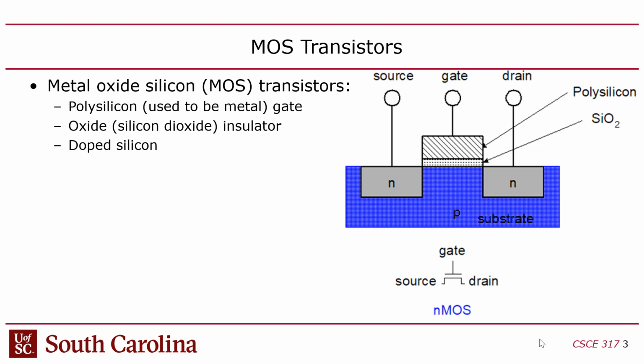And so even if you start out with a P-type silicon base, a substrate, if you put enough N dopants in, it'll actually reverse the doping. So this would have originally been P, but now we're going to reverse it to become N to create these diffusion areas. You guys with me?